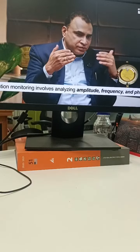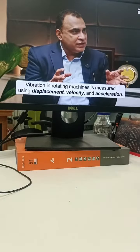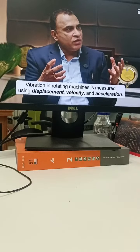Then a second question comes up when you do vibration monitoring, which is about what the parameters are. So in any rotary machine, when we measure vibration, we say vibration displacement, vibration velocity, and acceleration. These are the three parameters which we measure when we measure vibration in rotating machines.